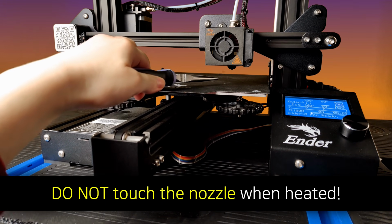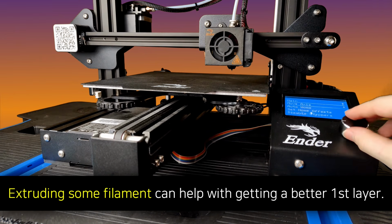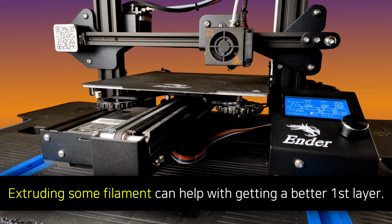I like to use a pair of pliers to grab the filament once it's done oozing out so that my hand isn't anywhere near the nozzle. Once the printer is done preheating, I then extrude 10 millimeters of filament to ensure that the filament is flowing and to also get a better first few layers for the print. Again, I am using pliers to grab the filament that's been extruded.